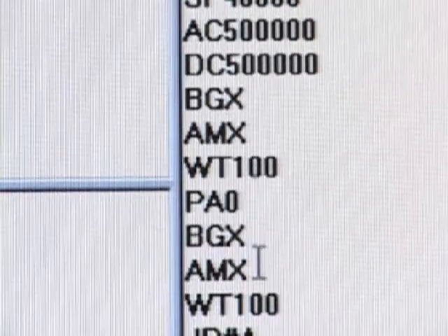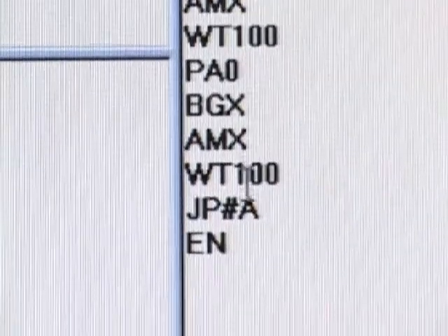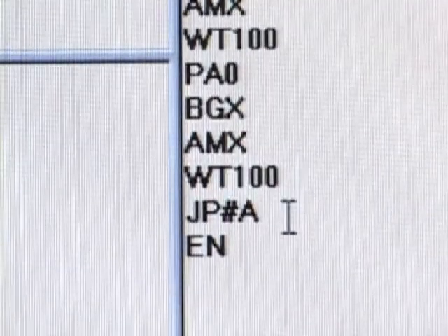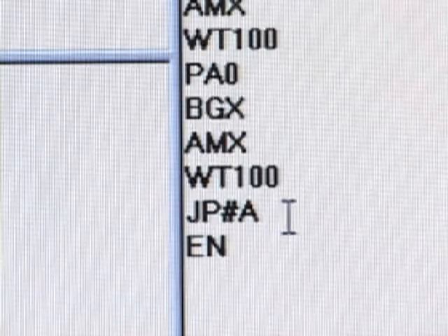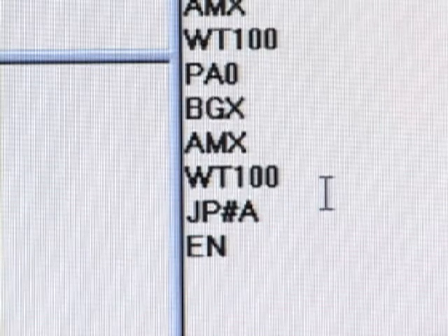Begin the motion, and after the motion is completed, wait 100 milliseconds and jump back to the beginning and repeat the whole process again and again and again. So this program, when it's executed, it would step the motor back and forth 2 revolutions.